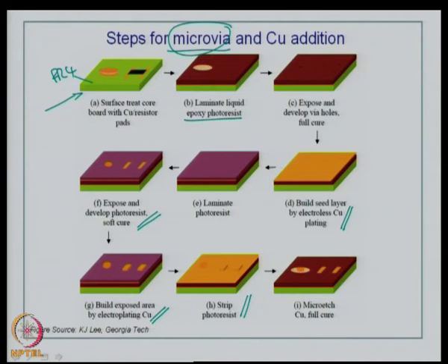So, you can highly integrate this particular embedded resistor and capacitor process with the SBU technologies that I talked about in one of the earlier modules, that is the PWB technology module. So, anywhere on the board you can design R, you can design C, you can create micro vias and you can connect them to signal planes or your ground planes and your active devices. So, we are talking here about micro vias of the order of 75 microns to 150 microns.